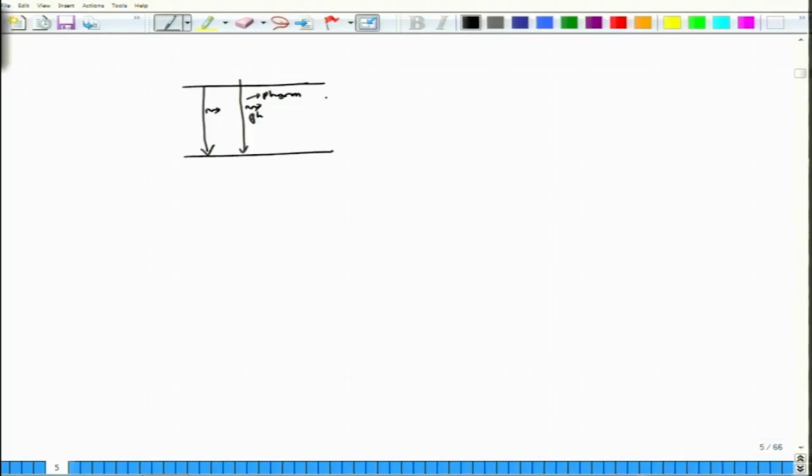And you might have some acceptor levels or donor levels sitting here, and these levels are the traps, as we would call them, and they are temperature dependent. Electrons can jump first to them, then jump to another trapped state, and then finally jump back to the holes and recombine. This is one additional type of transition, but there are 3 processes involved, and therefore the probability of this one will be quite small. Nevertheless, when it happens, it will lead to degradation of the laser performance, and therefore this should be avoided. These are the donor states or acceptor states which are deep lying, the impurity traps that contribute to unwanted emissions.